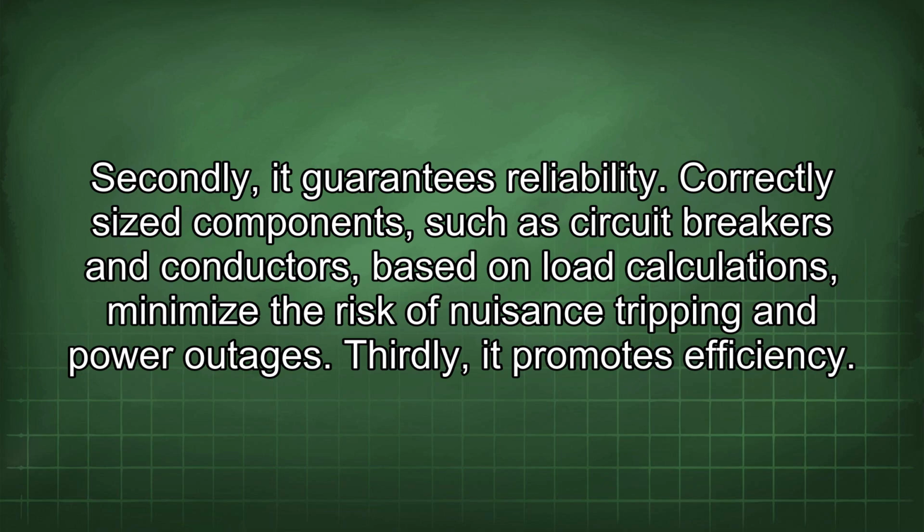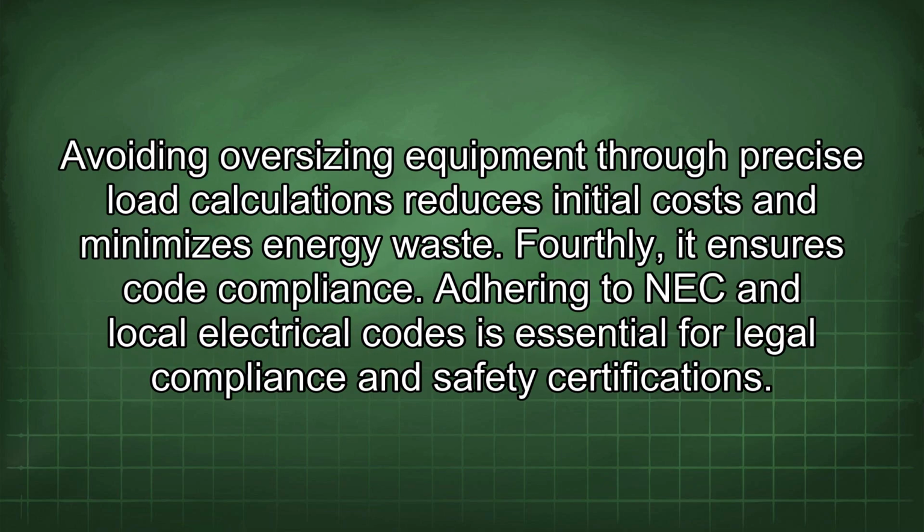Correctly sized components such as circuit breakers and conductors, based on load calculations, minimize the risk of nuisance tripping and power outages. Thirdly, it promotes efficiency. Avoiding oversizing equipment through precise load calculations reduces initial costs and minimizes energy waste. Fourthly, it ensures code compliance. Adhering to NEC and local electrical codes is essential for legal compliance and safety certifications.